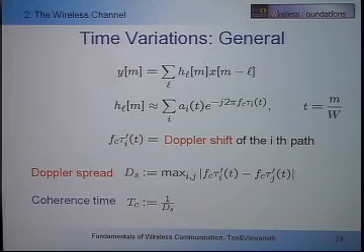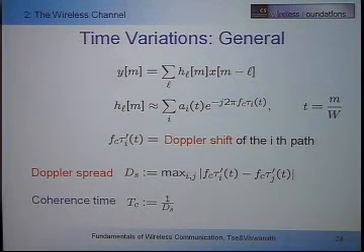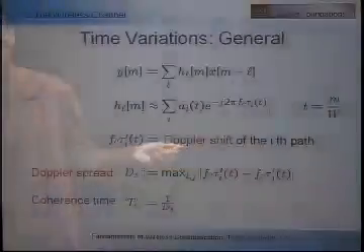There's actually a third source of variation of this channel tap, which is not explicitly written here, but it is there. Remember, what is this sum over? This sum is over all the paths that arrive in the bin. I always have quizzes every now and then, just to make sure people are on track. So that means there's another source of variation in this nth gain. Well, paths will change their delay, right? So as the delay changes, a path can potentially move from one tap to another, from one bin to another bin. Why didn't I take that into consideration? Maybe that's also important. Maybe I should not ignore that.